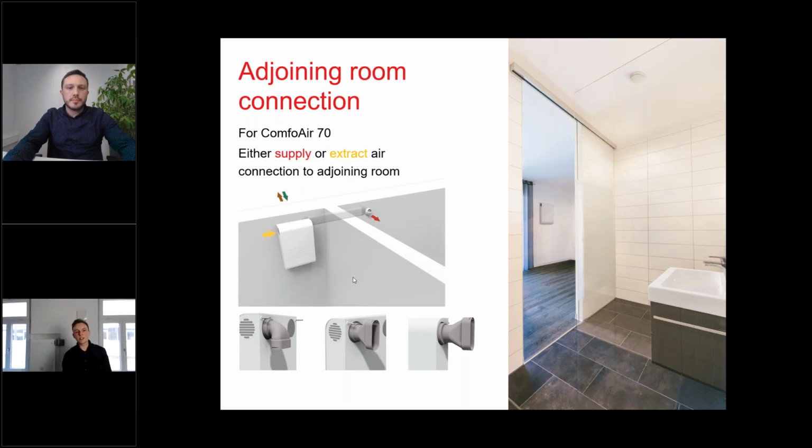You can connect these rooms with our air distribution system, either with the Comfort Tube 90, which is a round tube, or our oval tube, the Comfort Flat 51, using an adapter to the unit, as you can see below. The maximum recommended length for that pipe is 10 meters, and there we calculate two 90-degree bends. Each additional bend reduces the length by about 1 meter.